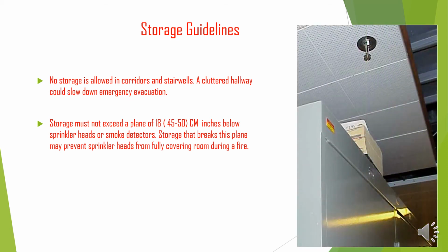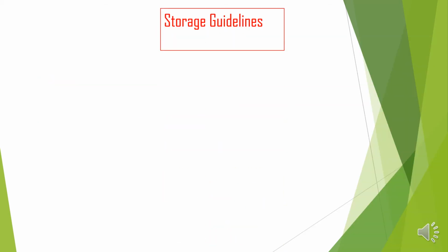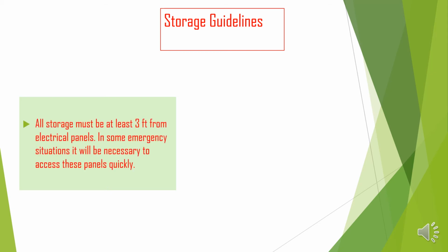As you see here, you have to maintain 50 centimeters from the fire sprinkler. This one will give water when there is a fire. What if you put something up to the ceiling, obstructing it from giving water? The fire will not stop. Again, the storage guideline is very, very important. You have to teach it to your staff, especially staff dealing with stores.